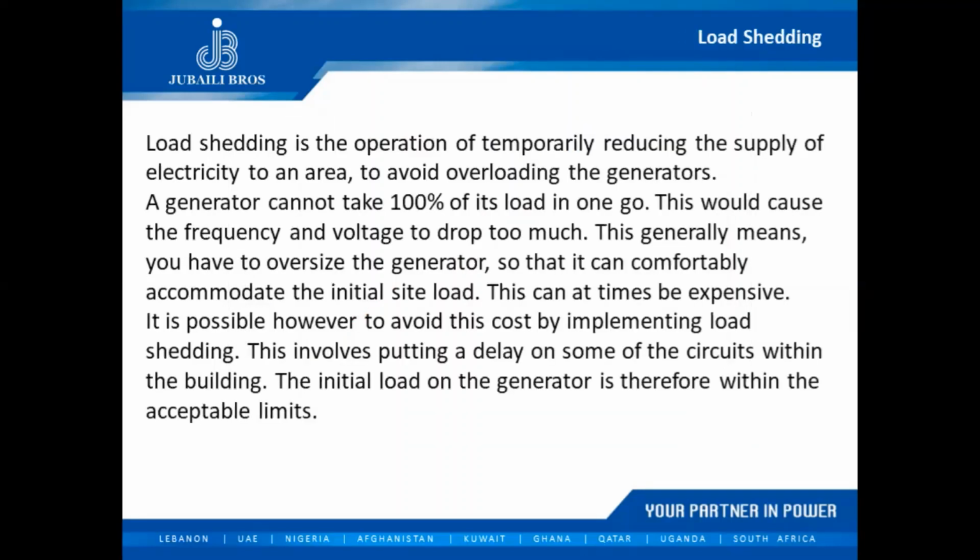Now, guys, this is the last topic we're going to discuss. I'm going to leave some room for questions and answers related to this, okay? Since we've answered other questions too as we were going. So load shedding. Lots of words here, okay? Load shedding is the operation of temporarily reducing the supply of electricity to an area to avoid overloading the generators. A generator cannot take 100% of its load in one go, typically speaking. This would cause the frequency and voltage to drop too much. This generally means you have to oversize the generator so that it can comfortably accommodate the initial site load. Okay, this at times can be expensive.